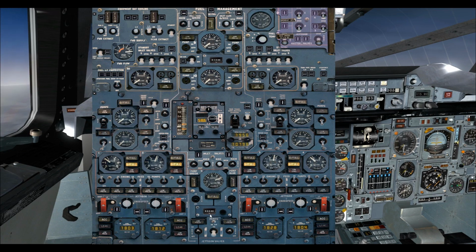And we can see fuel is now filling up tank 9, and it'll keep going until the load limit of tanks 9 and 10 reaches 1,000, and then the fuel will fill into tanks 5 and 7, and that will continue for the remainder of our descent.